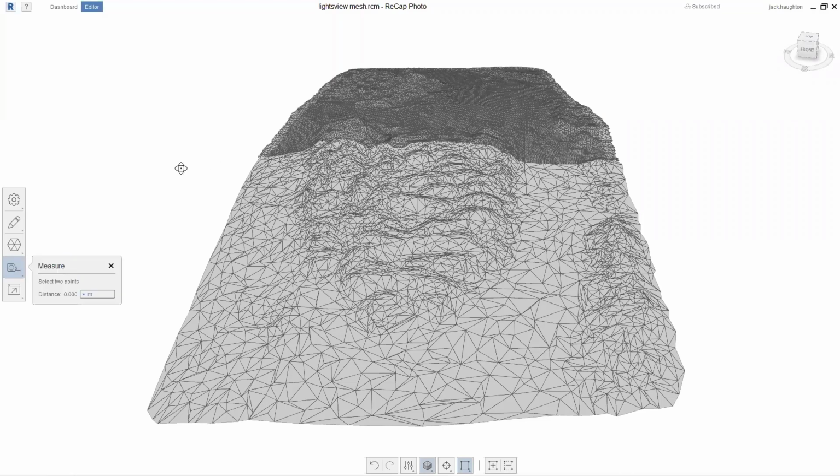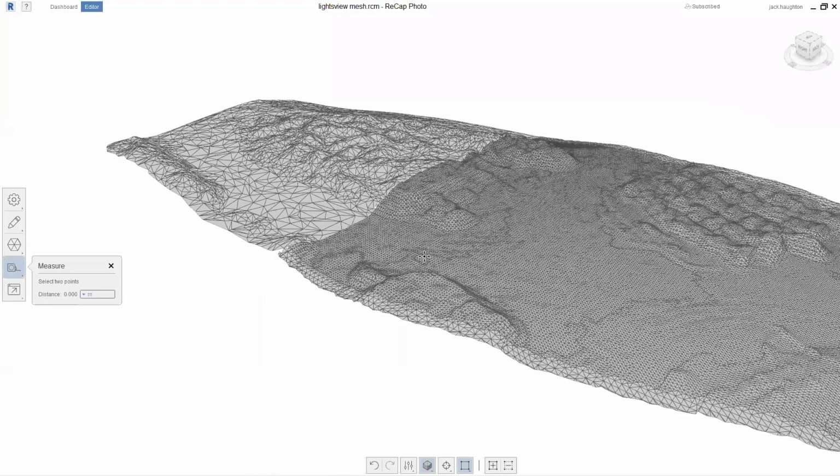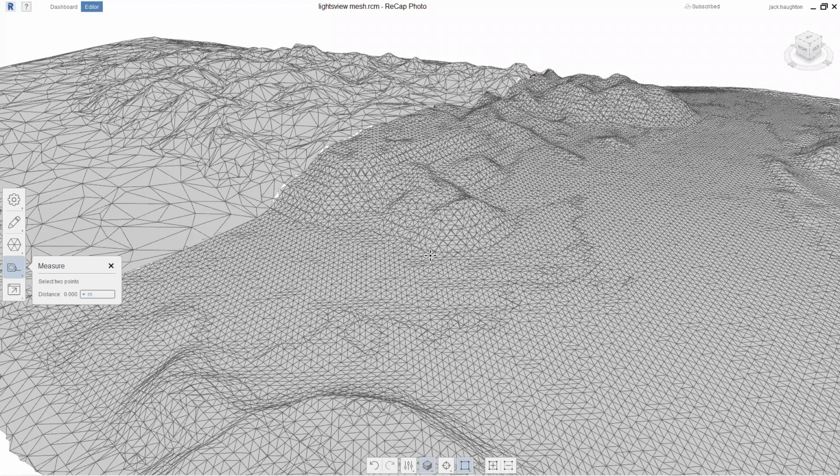Measure distance allows us to measure the distance between any 2 points. It works a little different to how some of the other softwares do. Instead of a drag to find it out, it's double click and the distance appears on the side here. By using this drop down here, we're able to choose between the different standards we want, different units. So you can select millimeter, centimeter, feet and inches, you can select between all of them.